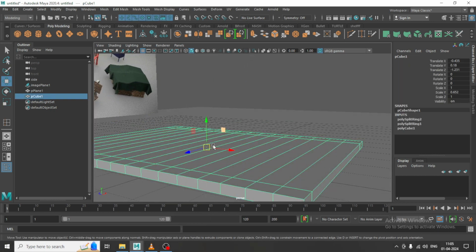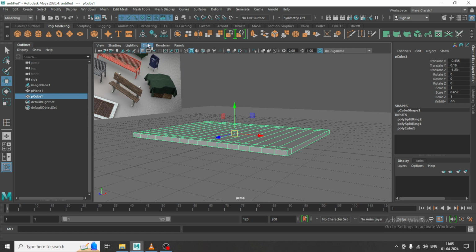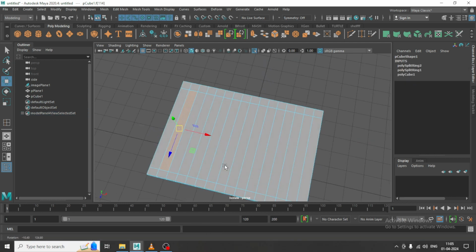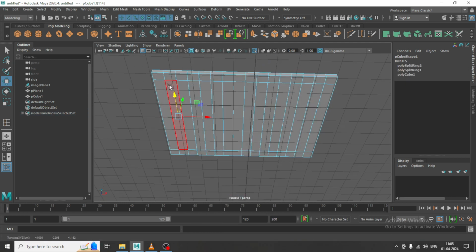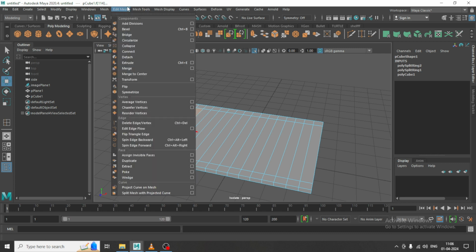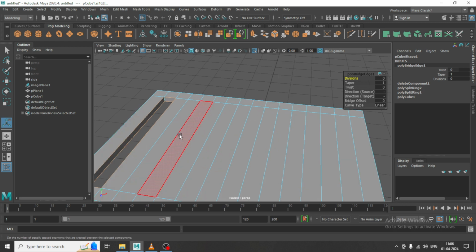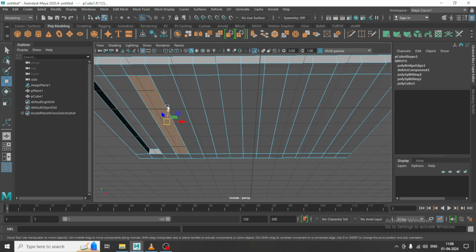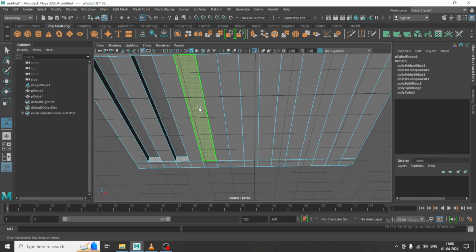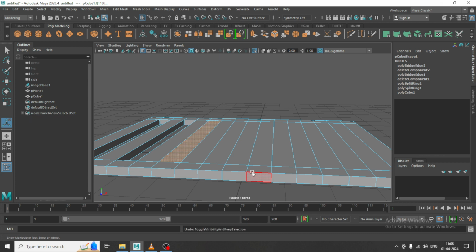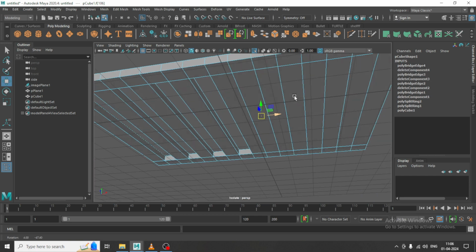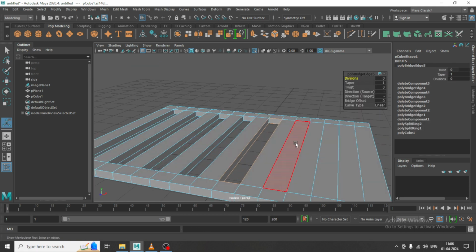and 5 will show you flat shade. Let's go to Show, Isolate Select, View Selected, because I only want to see this. I can select both of these, and you can go over here and give a bridge in this way. Select this and this, and if you press G, G is for repeat last command. You can just press G for repeat last command. That was your bridge.